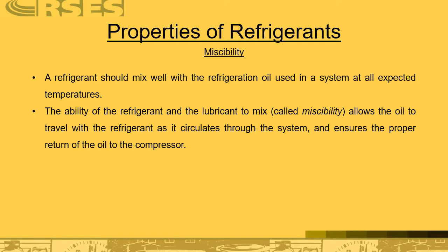It's always a metal container. If you leave that container open more than 30 minutes, that oil has to be disposed of because it is no longer usable. The only way you're going to get moisture out of POE oil is to change the liquid line filter dryer, period. I don't care how good your vacuum pump is, it will not do the job.